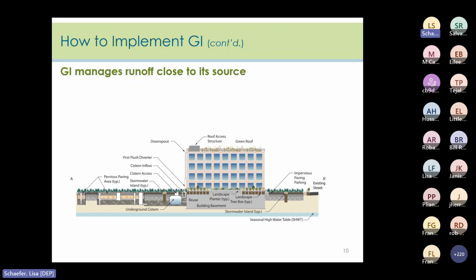All right. Now, this is an example of placing BMPs close to the source of runoff. This is just the elevation view. I'll show you the plan view in just a moment. But the project description that goes with this explains what's going on. A fully impervious 3-acre site in an urban redevelopment area is proposed to be redeveloped. The redevelopment will consist of a 1-acre building plus 40,000 square feet, or 0.92 acres, of parking areas and internal driveways, and also a 1-acre overflow parking area.